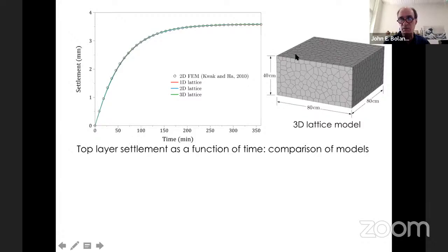Say it's in this box. We have a volume of fresh concrete, and at early age, the material is not quite a solid. It's more like a fluid, and the cement particles have higher specific gravity. They tend to settle, and the water within the mixture transports up to the free surface.